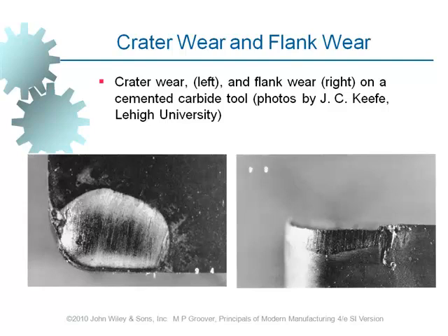And this wear continues as long as there is still a slight edge left here. As soon as this edge is removed, it's time for us to replace the cutting tool, because it does produce scratches on the surface of the workpiece, which isn't desirable.